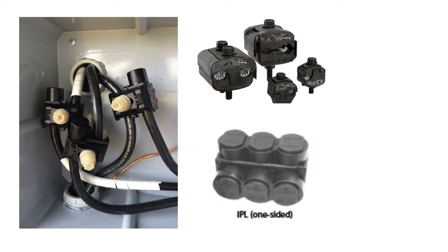But if the building can sit without power for a couple hours, most electricians will prefer to use the regular tap connectors where possible. Regular tap connectors are less costly and easier to reconfigure at a later date than their piercing insulated tap connector counterparts.